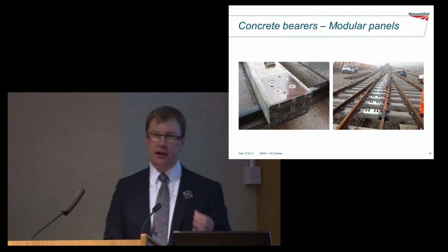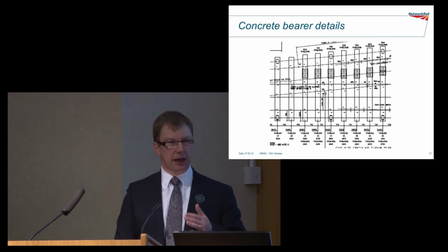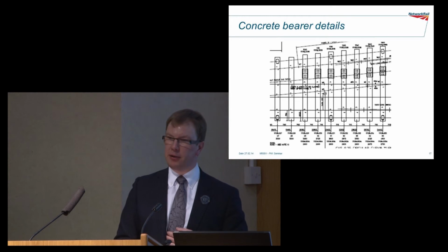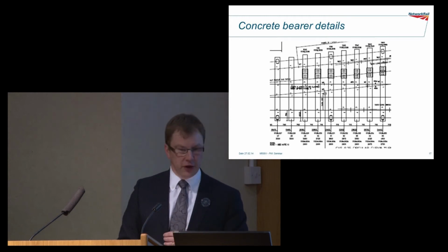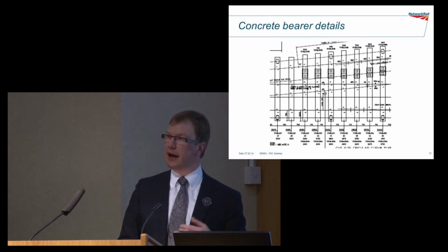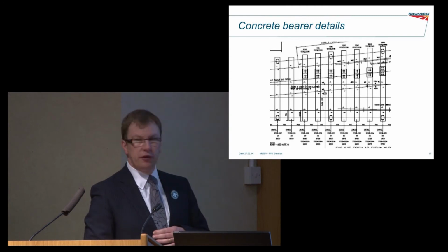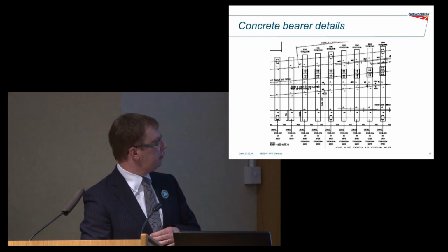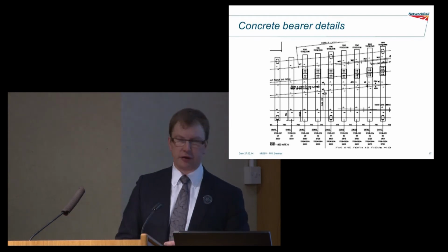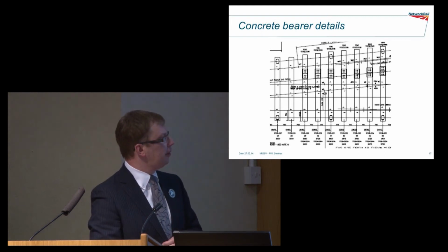So I said already previously, a lot of the design detail of the concrete bearers had been, I say lost, it wasn't within Network Rail control. So as part of the REPW drawings now, within the CAD version, you can click on and you can actually pick up the housing positions from that CAD drawing. So again, we've got control of that data. So going through on the through route, the housings are here and they're all quite straightforward. When you start to go round onto the curve route, on a turnout route or a crossover road, then things get a little bit more complicated.